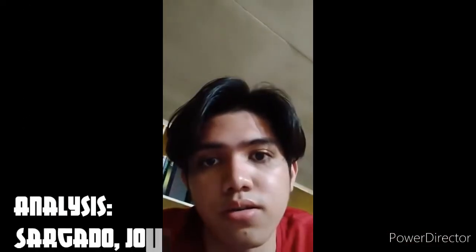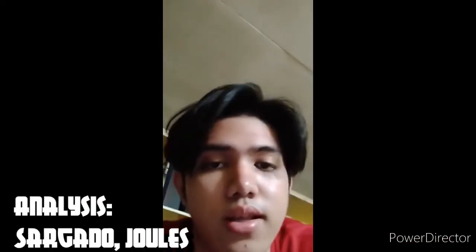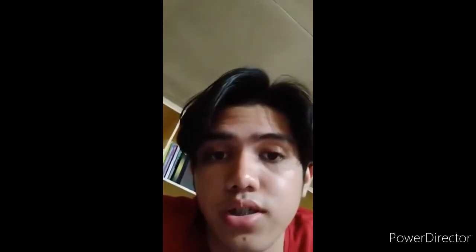I'm Joules Sargado. I'm here to talk about the analysis of lab activity number 6. Parallel circuits are used for creating more complex networks like multi-way switches. Upon using a voltmeter, we can figure out the value of the individual voltage of the resistor, and by looking at the ammeter, we could have the current's value. The voltage across resistors in parallel will be the same for each resistor.